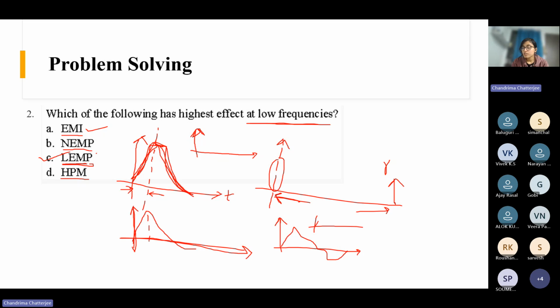Okay, so what do we do in Fourier analysis? We represent one waveform which is irregular in terms of sines and cosines. There is one fundamental frequency omega naught, and then it has some multiples of omega naught, maybe 2 omega naught. It may also have 3 omega naught, 5 omega naught, based on the shape. From that we get the frequency components that these waveforms have.